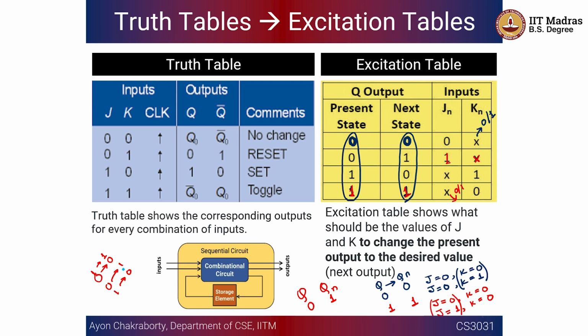It's better to remember it like this, because don't cares sometimes help you make the simplification much easier, right? Because in K-maps, for a much larger circuit, if you have these x's, it is much easier for you to group terms, right? Of course, you can take both of them as toggles.